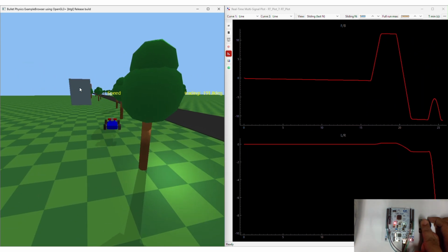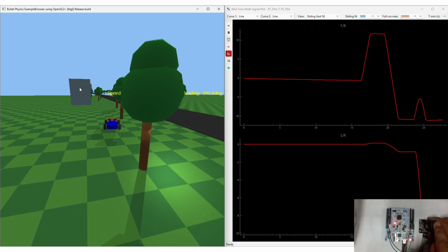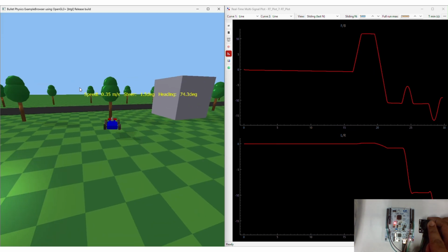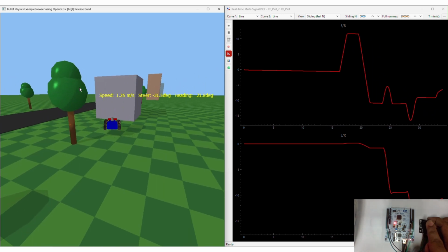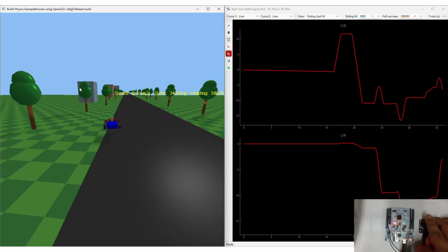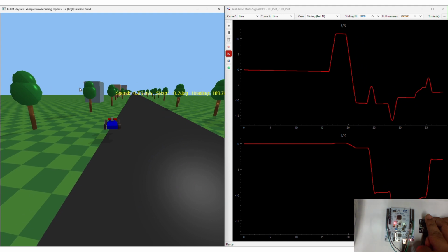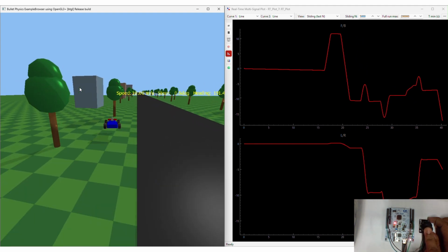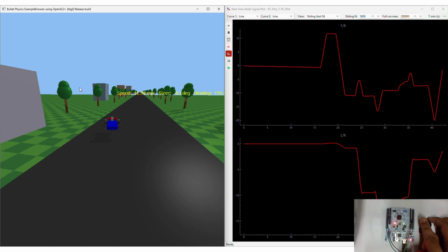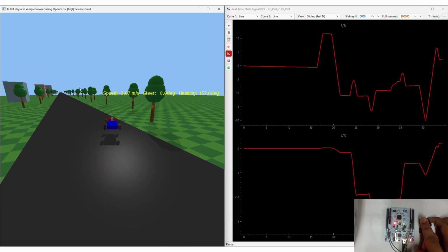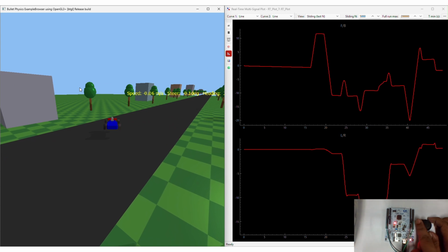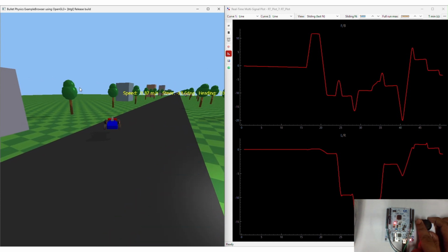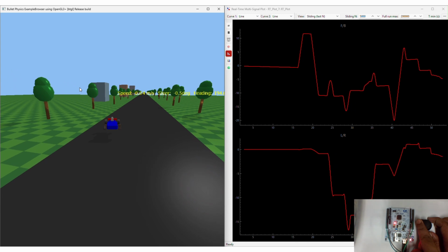The joystick values are acquired by the STM32 through the ADC, transmitted over the serial interface, processed by the Python bridge block, and immediately applied to the virtual vehicle. You can also observe the speed and steering signals updating continuously in the RT-plot window during the simulation. This demonstrates seamless real-time communication between the STM32 hardware, TwinSimulate, the Python bridge block, and the 3D virtual environment.